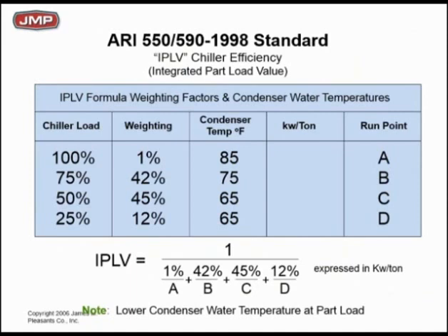So what we're suggesting to you is, why don't we take this approach and look at pumps? I can make a pretty good argument that as your load profile changes for hot water and/or chill water with two-way valves, your flow rate in GPM is going to change. It may not be direct, but it's going to change along with the same change in your load in BTUs, whether it's heating and/or cooling. I'm going to suggest that we use this load profile when we look at pumps.